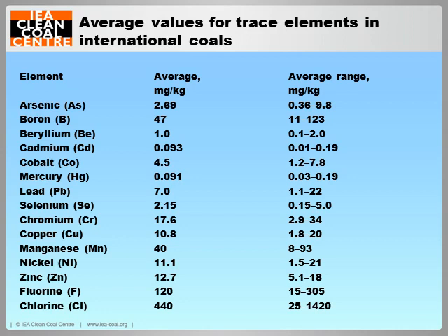The amount of trace element emissions from coal combustion has been reported to be dependent on the modes of occurrence in the coal. Elements associated mostly with the coal organic and sulfide fractions tend to vaporize and then absorb on the fine particles when the flue gas temperature drops. On the other hand, elements combined mainly with the other minerals remain in the ash. One option for controlling the release and distribution of the latter is to remove them prior to combustion by coal cleaning. Pre-cleaning or washing the coal is a currently used method to reduce some trace element emissions.